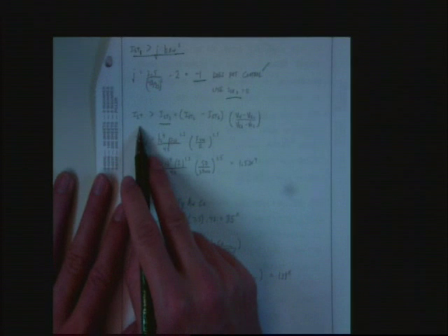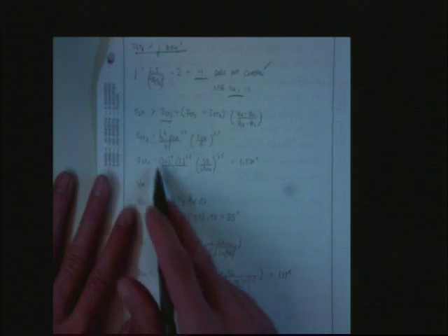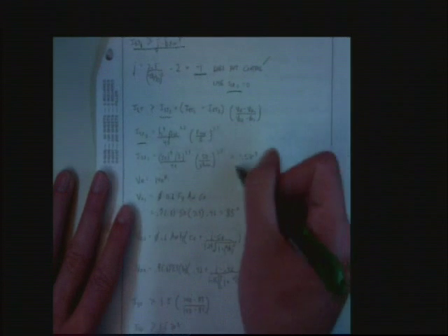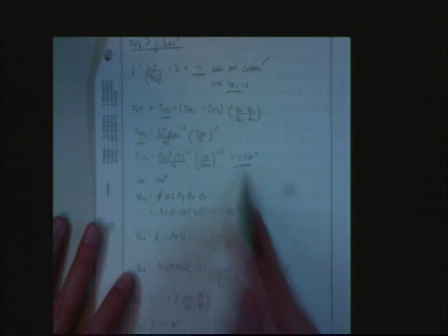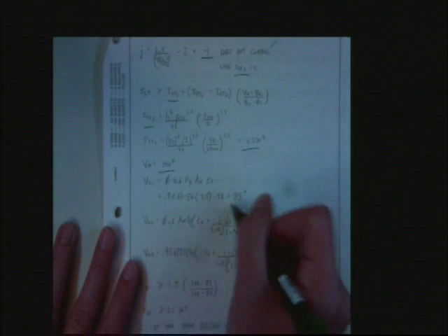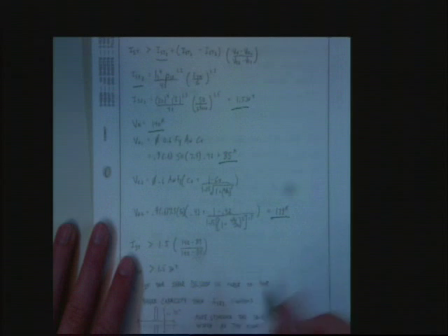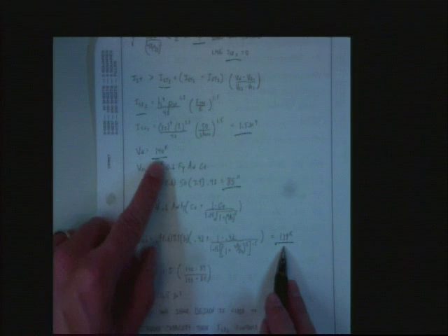So then we go back to this equation, the big nasty equation I introduced today. And we solve for IST2. And finally, ladies and gentlemen, we find a positive number. Yay. But look at the value. 1.54 inches to the fourth. I could sneeze and get that. It's nothing. But we'll keep going. So we do our shear capacity is 140. We calculate what our V sub C1 is. We calculate what our V sub C2 is. And look at this. They're almost the same. Why?